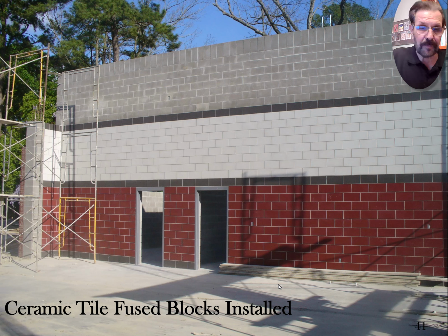One other thing I could mention before I leave, and I'm getting into details, I guess, overdoing it here, and that is that those doorways that you see in there, there's metal door frames there. Those metal door frames, you stand them up before you build the wall, and so a carpenter often does that. I've done a bunch of these where I basically had to put sheets of plywood in place of a door to hold the whole door frame together, so that I can then screw some braces into the concrete on each side to hold that thing in place for the bricklayers, the masons, so that they can install their masonry around it, and they put ties into the mortar as they go.